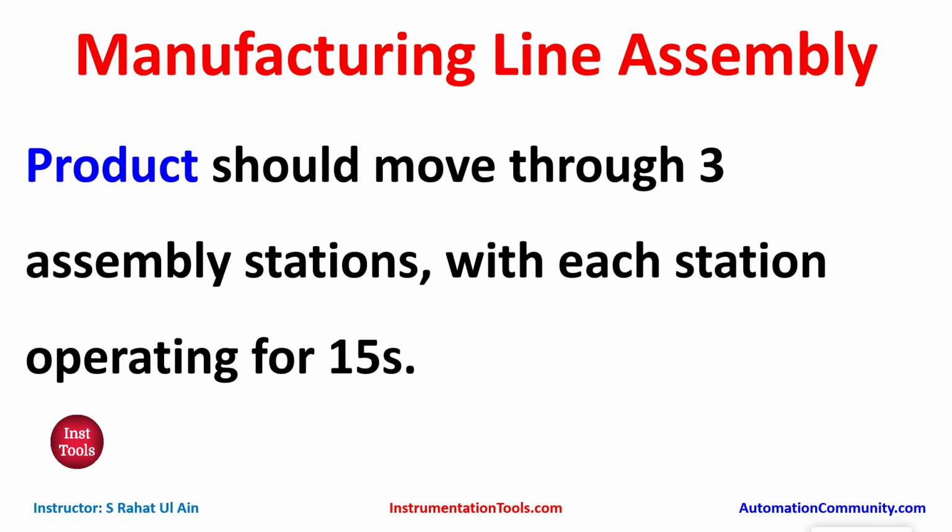So the presence of the product will be detected by a proximity sensor, and that proximity sensor will stop that conveyor for some time, that is 15 seconds. So this proximity sensor will stop the conveyor belt system for 15 seconds, and it will activate the components that will do the service at that particular assembly station.